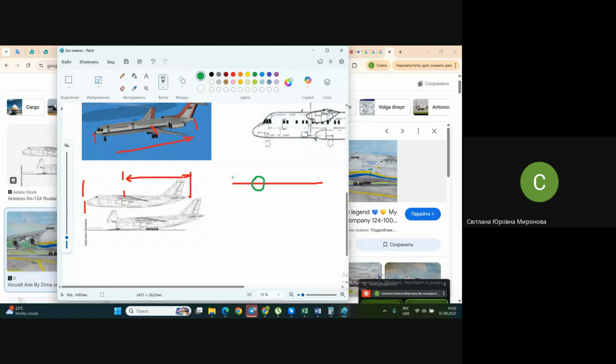Even if we imagine that all other weight of the airplane is distributed equally all over the fuselage, do you imagine that passengers or cargo are distributed approximately equally? Engines, wings, stabilizer are jointed masses, additional masses acting approximately concentrated somewhere along the fuselage.